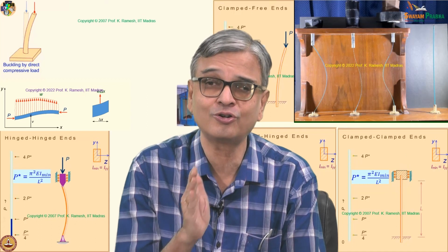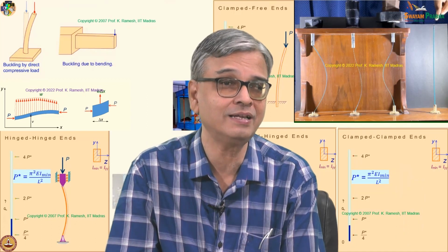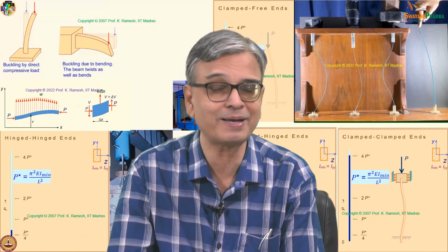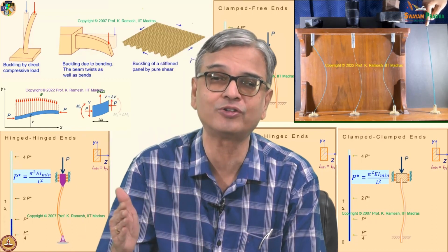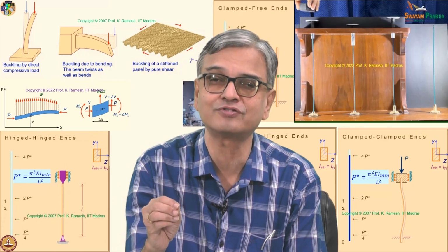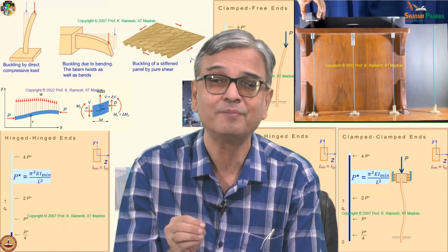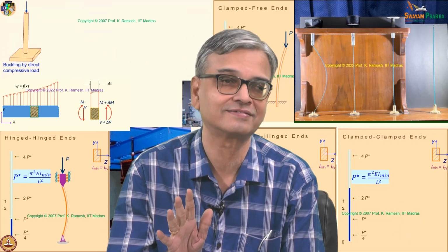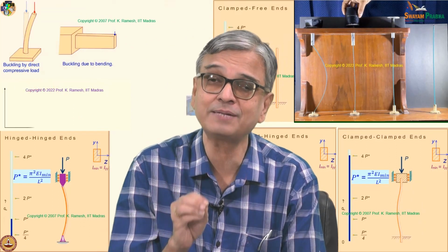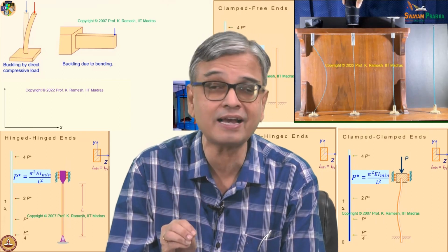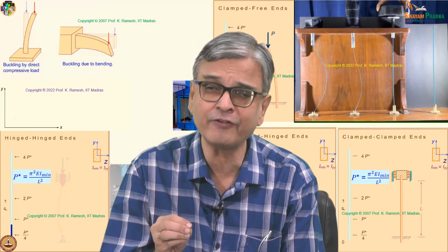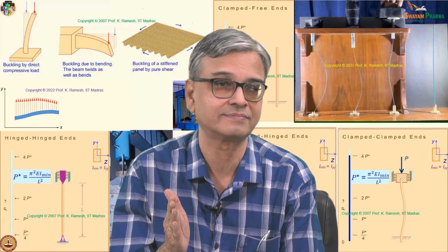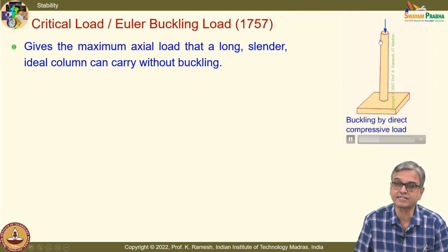See, in this course, to make our life simple, we have said we have an elastic continuum. Our mathematics, we could develop so beautifully. When delta x goes to 0, there was material available. But real materials, how are they? They all have defects. So, one of the perturbations that can precipitate buckling can come from inherent defects on that column. See, I have a circular cross section.